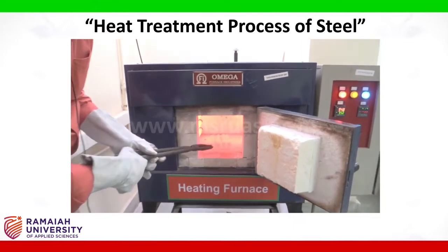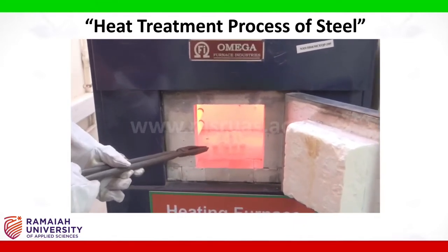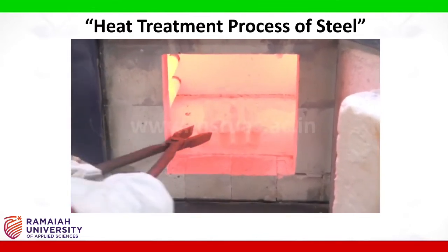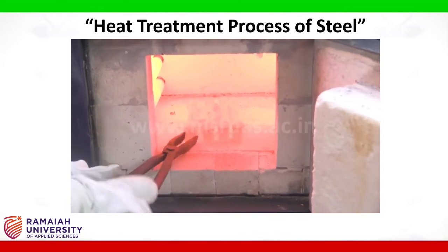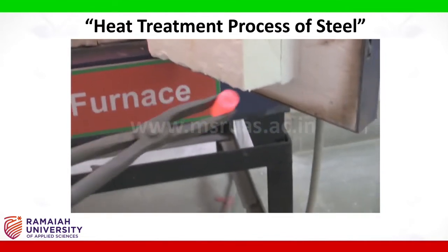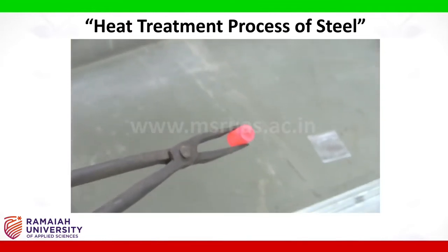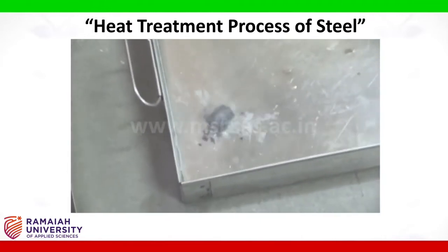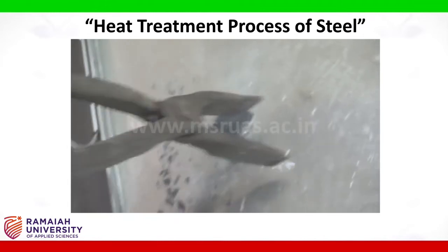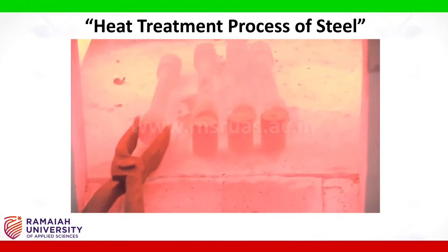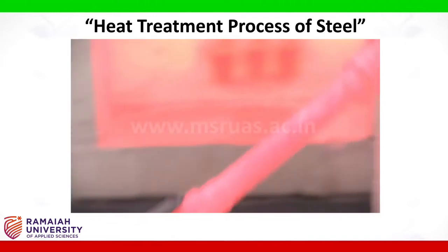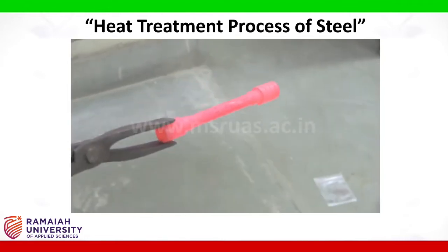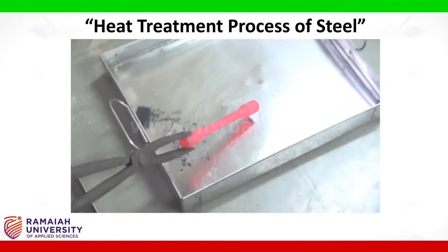As you can see, all the samples are heated at 950 degrees centigrade for 1 hour 15 minutes. First sample, I will take it out and I will carry out the quenching process. Here you can see that water is there. Tensile sample, and quench it.